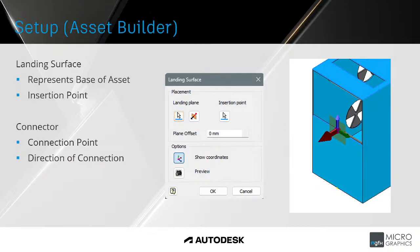And on this, we will also specify an insertion point. Essentially, where is the asset attached to your cursor? So we could have the insertion point on the image on the right here, that midpoint along the bottom edge of the model. And so the cursor would be attached to that point when you move the asset around in your assembly, when you're inserting it. Then secondly, we need to specify a connector.